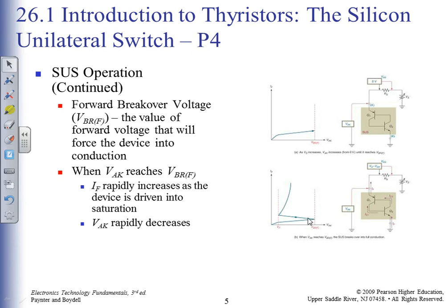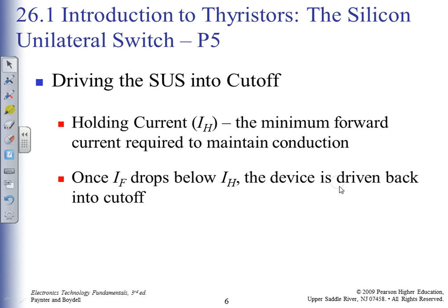And what I'm going to do is when I turn on, I'm going to have some negative resistance characteristics. See that curve there? It has a negative slope. So it's going to have a negative resistance when I turn on. And turning on, that's an important thing to do, right, for switches? Yeah. Relatively important. It'd be nice if that graph was better looking. There's some holding current to keep it on. If the current falls below the holding current, it goes back to being off.